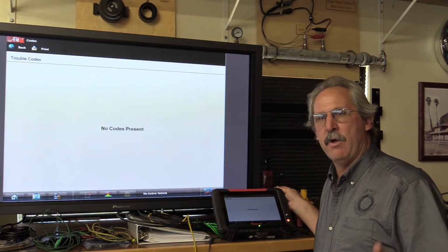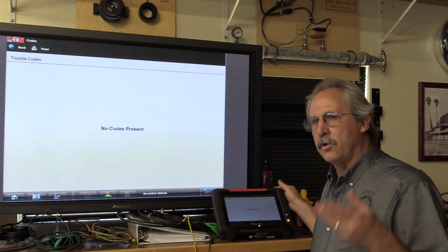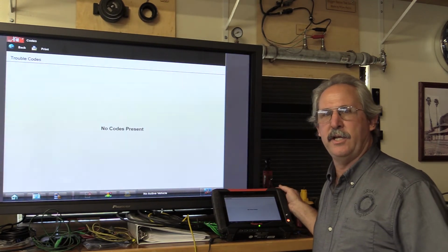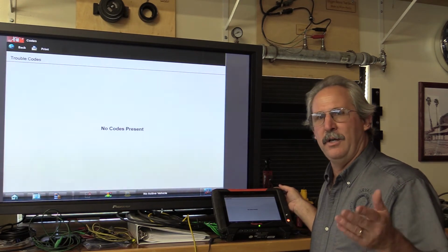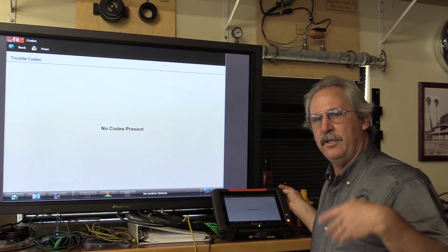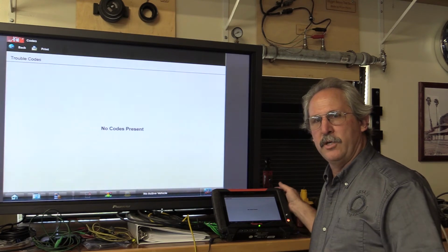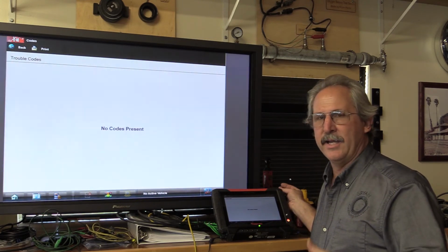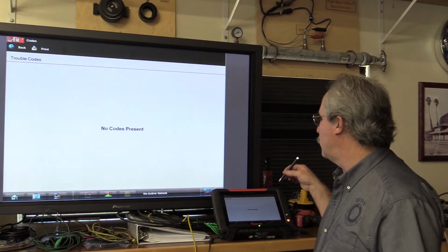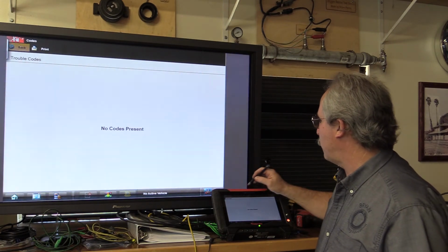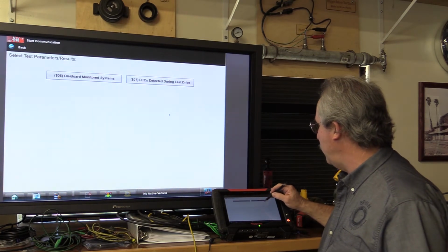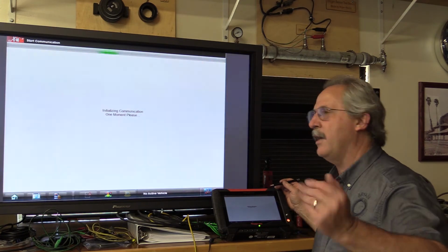In actuality, you have a hard circuit fault. Hard circuit faults are among the easiest things to diagnose because it's a simple electrical circuit code. Get the information on which circuit's out of range, get the wiring schematic, and troubleshoot the circuit. So if I look here, that's mode 3. If I come into mode 7, my pending codes, we'll see I have no code.